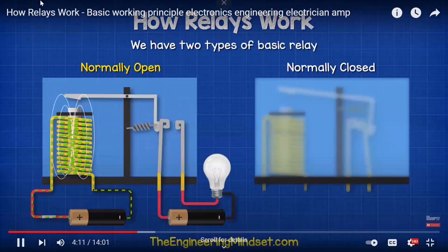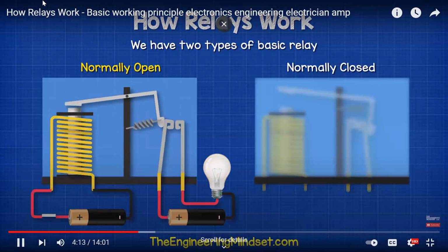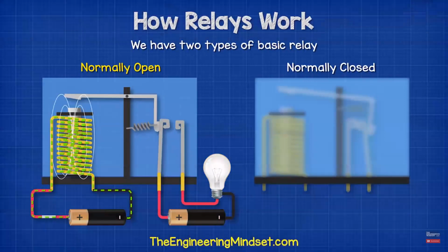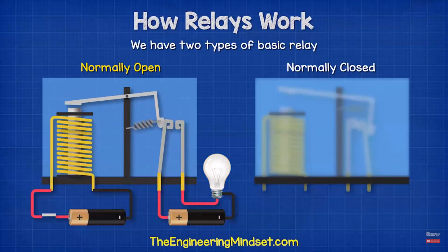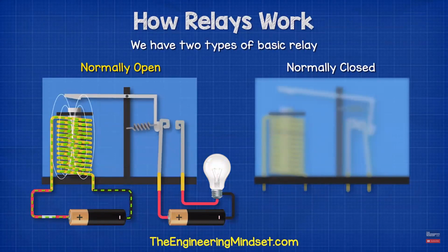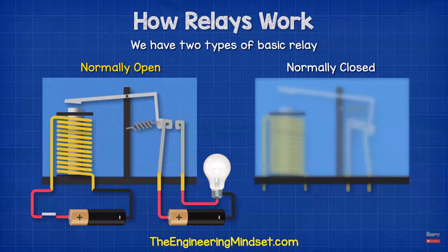However, when a current is passed through the primary circuit, a magnetic field is induced in the electromagnet. This magnetic field attracts the armature and pulls the movable contactor until it touches the terminals of the secondary circuit. This completes the circuit and provides electricity to the load.